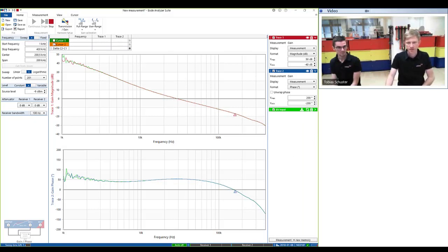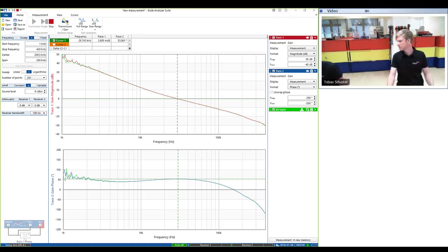Let's see what the phase margin is. If we go to 0 dB here, we have a phase margin of roughly 50 degrees, and we can now look at the step load response of that system and check if it matches the 50 degrees phase margin. Can you please switch on the load? I just need to switch on the waveform generator.